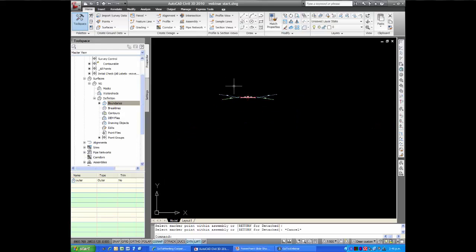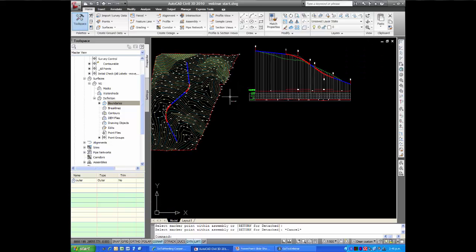Okay, I'm going to zoom back out here. In relation to the rest of the drawing, those assemblies that you make are quite small, so many people will often make a little circle to put around them, just so that you can know where they are in your drawing when you're trying to find them. Oh, I've just done that here. Okay, so we're ready to make our corridor.